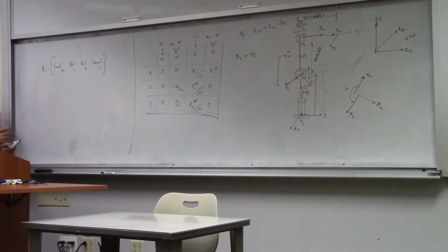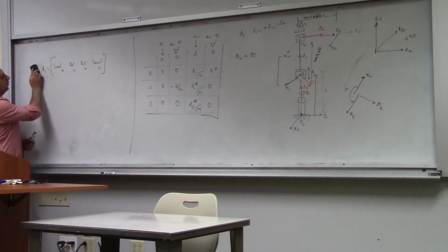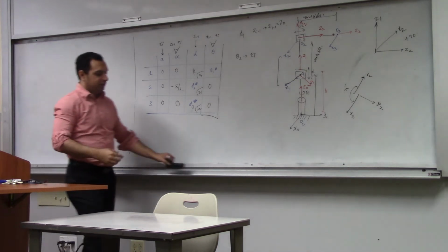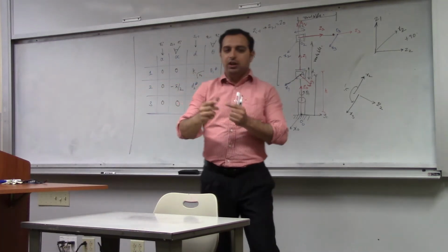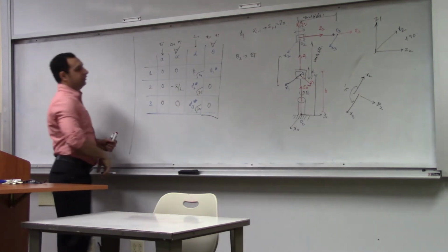So that is one of the drawbacks, that you cannot do any rotation about y. If you come across a manipulator where you have an axis which has a rotation or translation along y, you'll have to rearrange the axes and make it along x or z so that you can measure it.